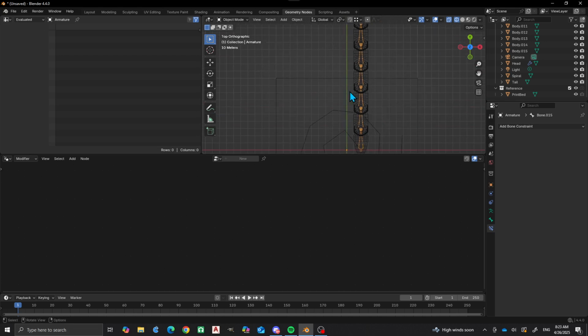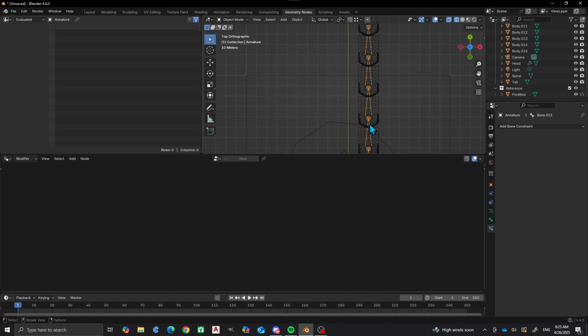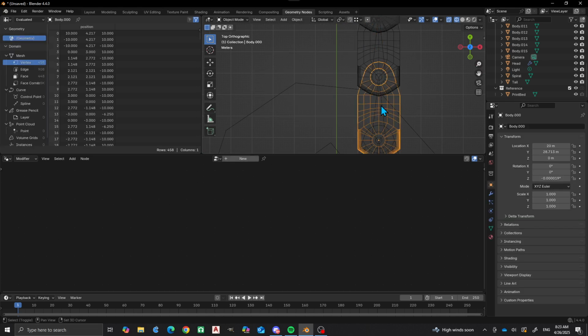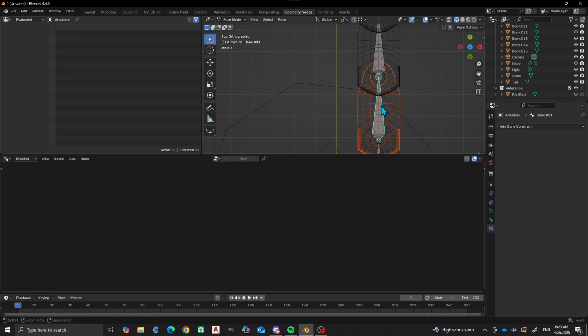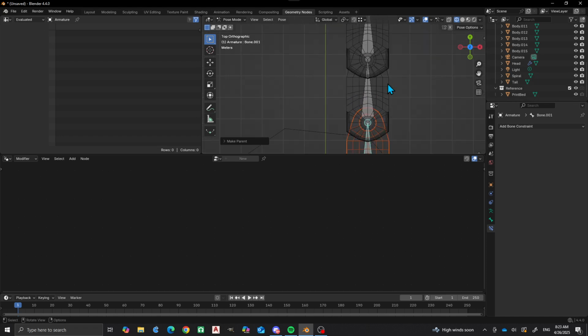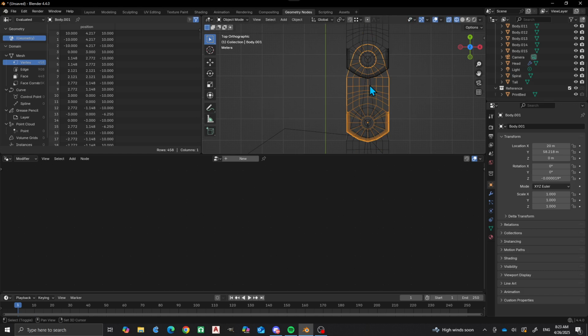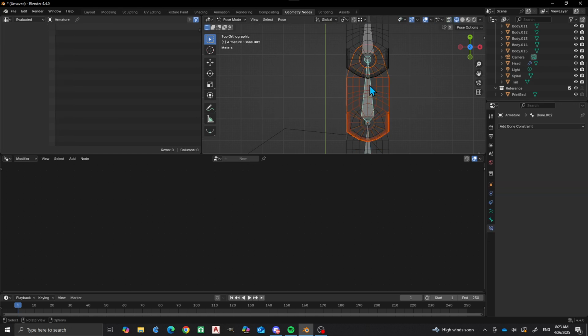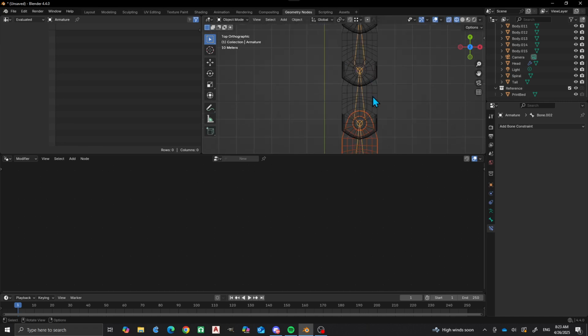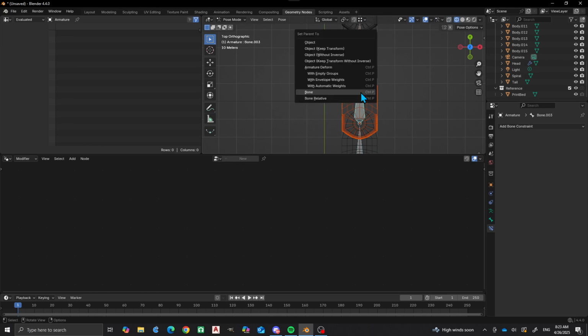So I've got all those objects now where they're perfectly in place, okay? So it was a lot of repetitive work that I did, but now it's on to the next part, and that's making sure these are parented. So now I just do the same thing. Now I'm going to say I want it to parent to bone, okay? That way we're not doing any weird weights or anything like that. These are not going to be flexible objects. They're going to be rigid objects. So that gets to be a really repetitive process, but you know what? This is necessary for getting all this stuff put in.